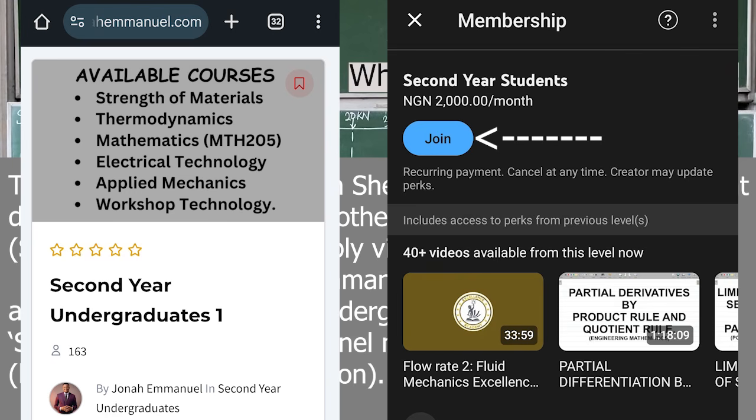How do you describe this point? This point is 3 plus 2. That is 5 meters from which end? From this end. This end was labeled A. You can say, and occurs at 5 meters from A. That's it. So this is the first condition. It's called the position of maximum bending moment.